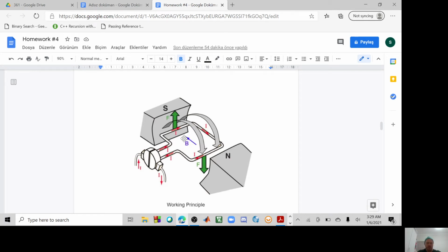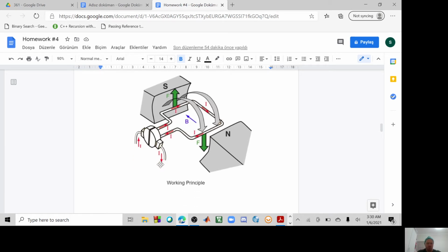Electromagnetic forces acting in this machine. I want to mention this. We have electric current which is coming in from this side. When electric current passes through a coil, this one is the coil, a magnetic field, or the magnetic force, produces a torque which turns the DC machine. So we have a magnetic force which acts perpendicularly. It is perpendicular to the B field, and also it is perpendicular to the current.